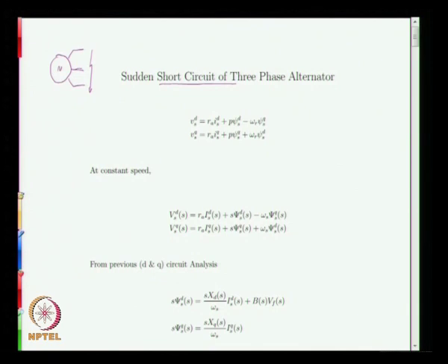It can be noted that this is done as a regular test in order to examine the behavior of the alternator and also to determine alternator parameters, more specifically the d axis ones, all those terms that we have defined now, that is xd double prime and xd prime and td dashed o.